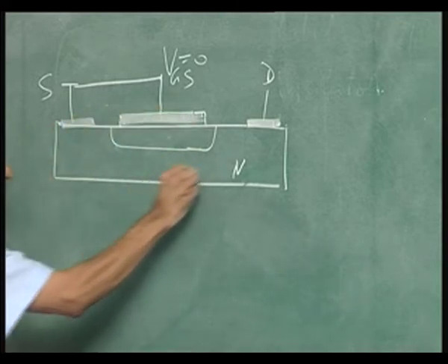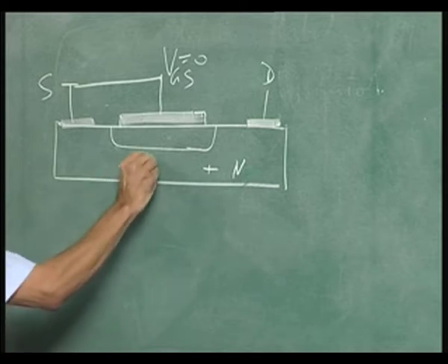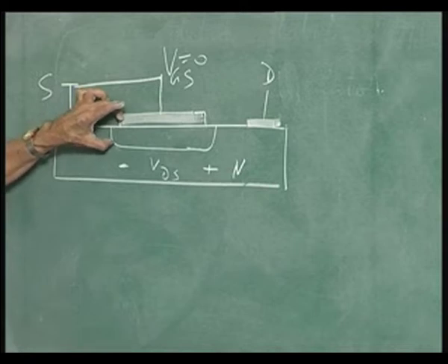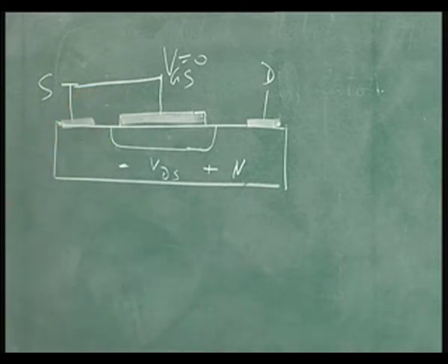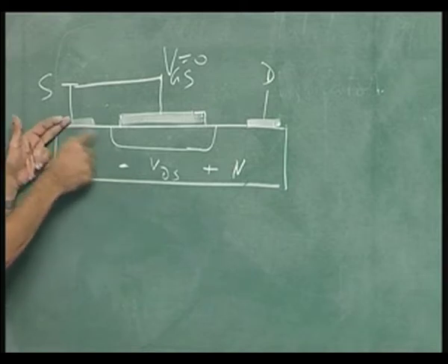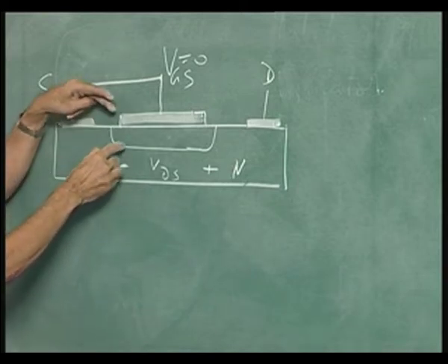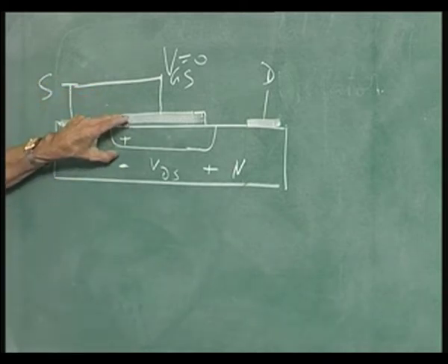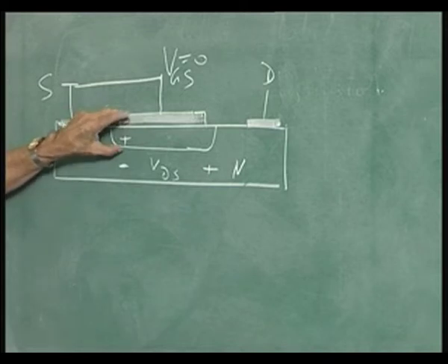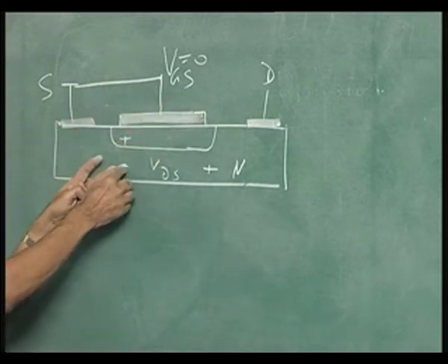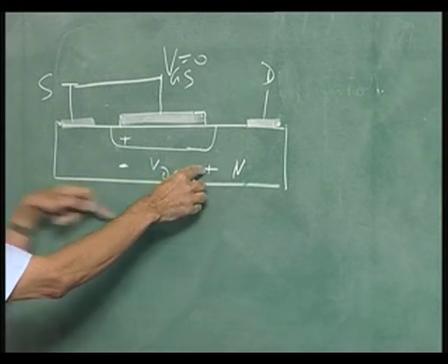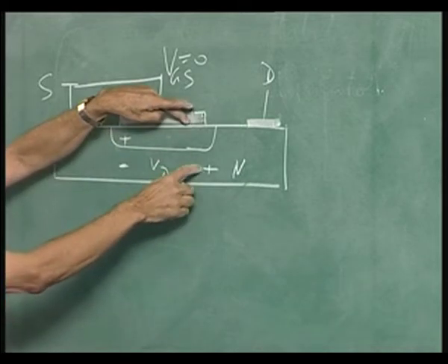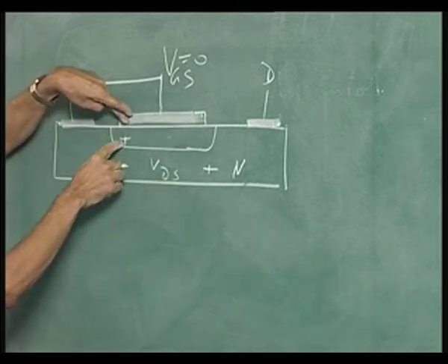Now, if there is a drop like this here, VDS, what is the potential here? I am neglecting this drop here. This is negligible, so this is the same potential here. Built-in potential polarity is plus minus here, plus minus here. Now, if I move from here to this point, what is the potential? That is what we are trying to see. In this region it is only VBI.